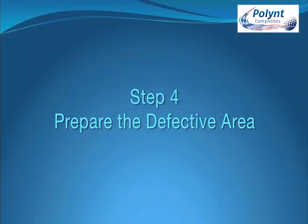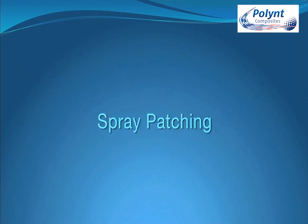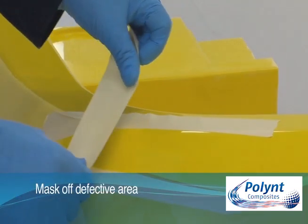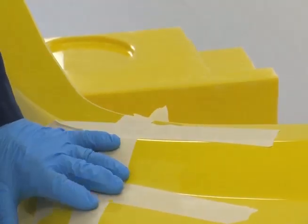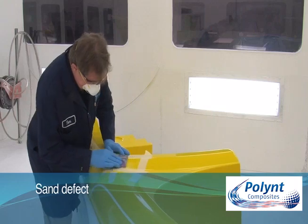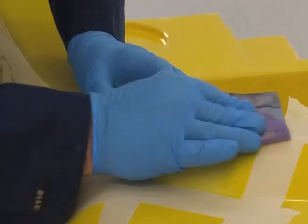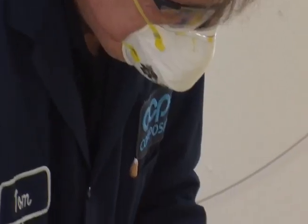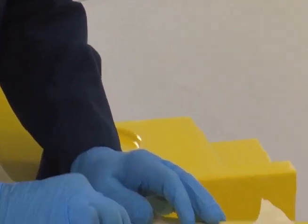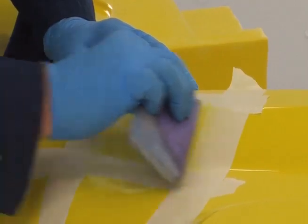Step 4. Prepare the defective area. First, let's look at spray patching. Mask off the area around the defect with tape. Sand and/or grind out the defect using 220 or 320 grit sandpaper or a dual action sander. Also sand some additional area around the defect.